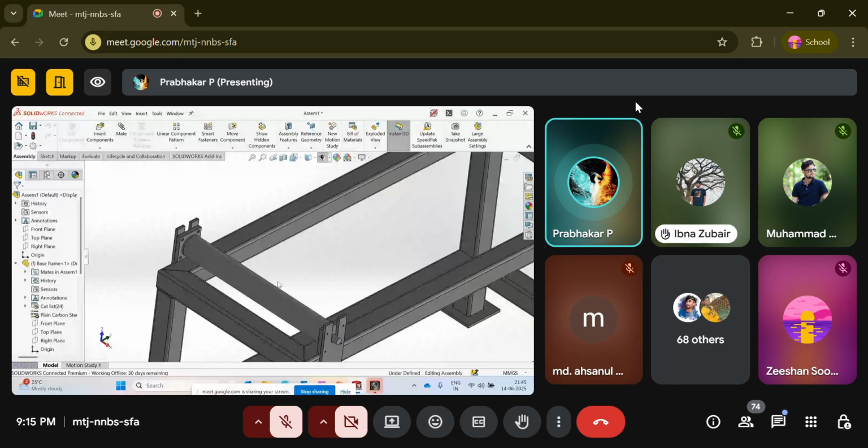And even medium carbon steel can be case hardened, like gears, dowel pins, where the surface which is in contact needs to be hard, and the inside core should be soft. For such material, you will be doing the case hardening. Full hardening will be done for most of the cutting tools. Wherever the punch and die are used, it will be completely hardened because we have to regrind it.